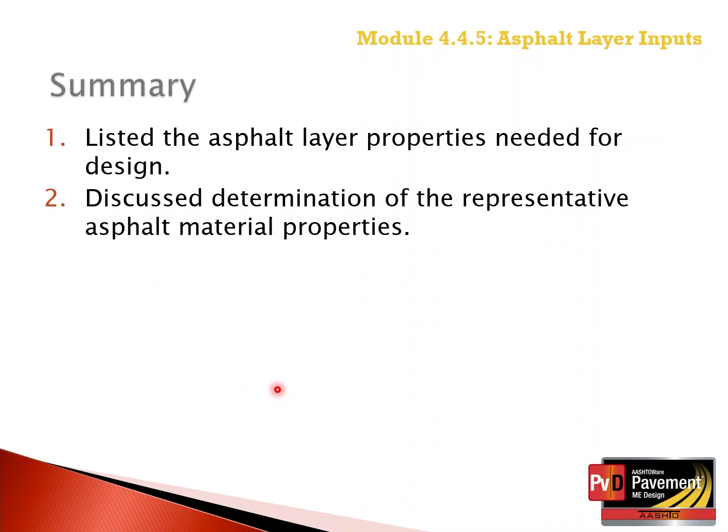The second outcome was to discuss determination of the representative asphalt material properties. Again, the asphalt properties determined at the time of construction represent short-term aged conditions and do not represent mixture design conditions in the laboratory.